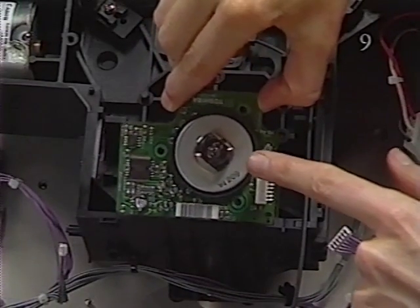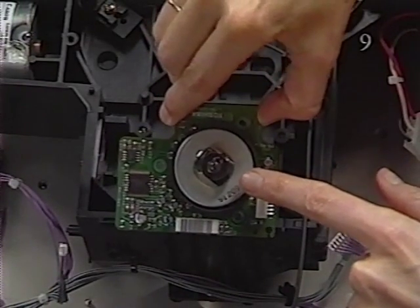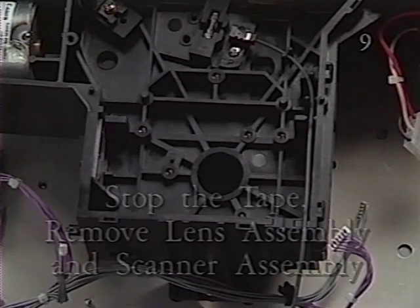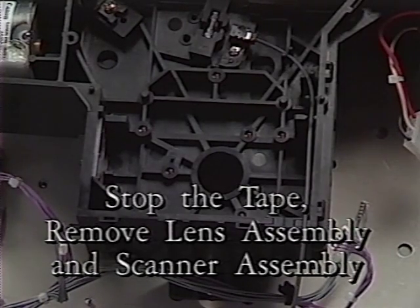Caution: do not touch the scanner assembly. If the mirror is touched or becomes dirty, it must be replaced. This part cannot be cleaned. Stop the tape and remove the lens assembly and the scanner assembly.